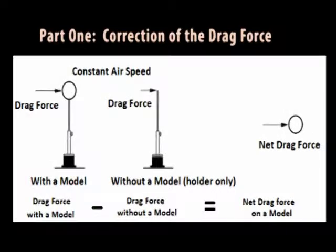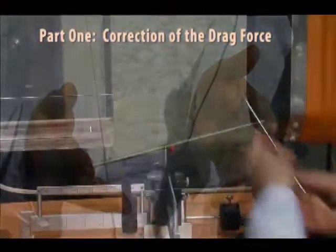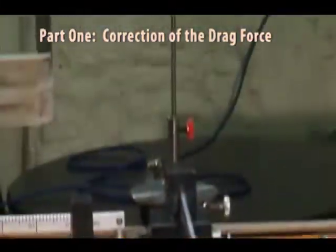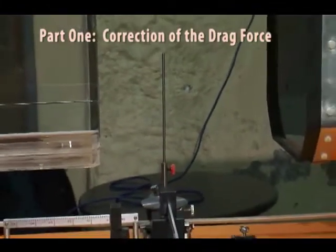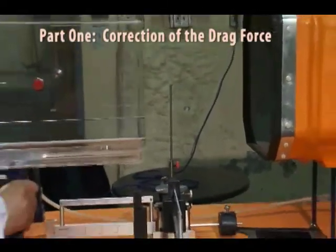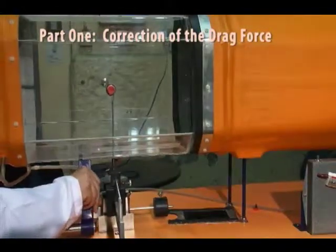In order to give accurate results for drag force measurements, it is necessary to measure the net drag force on the model by subtracting the drag force resulted from the support rod. Therefore, run the drag force test on the spare support rod at the same testing conditions and plot the support rod drag versus airflow speed. The appropriate drag force of the spare support rod may then be deducted from the total drag forces measured for a particular model and support at a given airspeed to get the net drag forces on the model at that speed.